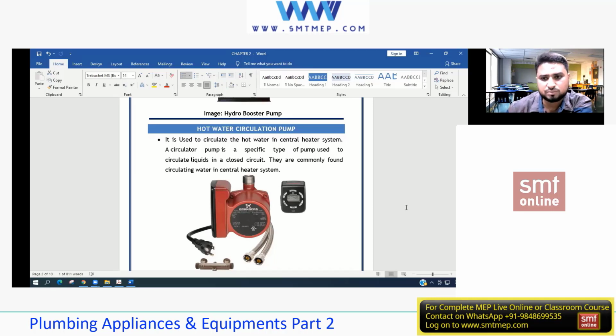It pumps the water, and it always forms a loop over here. For example, it's always rotating, and in this circle we have, say, 1, 2, 3, 4, 6, 7, 8 fixtures connected to it. You can visualize it with a clock, with 12 numbers, 1, 2, 3, 4, and all this is a loop. So 1 is one fixture, 2 is one fixture, up to 12 fixtures, for example. When anyone calls for a fixture, at the very next moment we get the hot water, because it is always rotating in this direction. Yes or no? Yes. But why is it rotating? That is also one question.